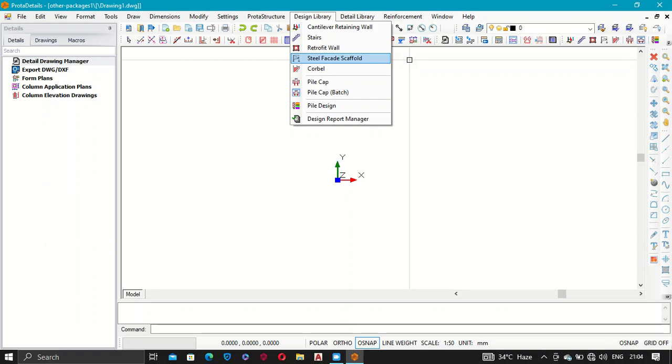So you can use this to design an effective scaffolding structure. Scaffold is not just something where you purchase steel pipes and decide, okay, fine, this steel pipe can work, and you just use it to do your construction. In actual sense, you're supposed to do a design for it first, for you to decide the diameter of the pipe you're going to use as well as the thickness, depending on the type of steel you're using.